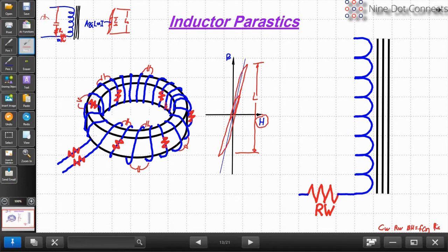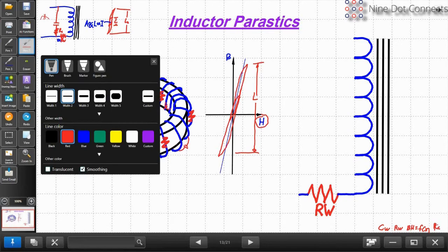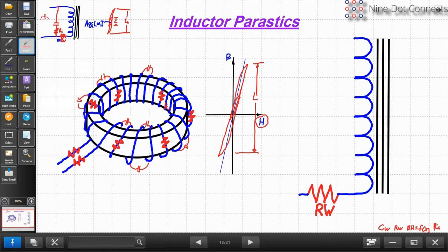How do they express themselves? Well, if you have two windings, a unity gain transformer that's tightly locked, and you put a capacitor on the output, what do you see on the input? Well, the capacitance on the output is just mapped to the input. You see the capacitance. So the little capacitors on each individual coil all map back to the equivalent of being on the source. So we end up seeing a large capacitor across here that's the equivalent of all the little capacitors.